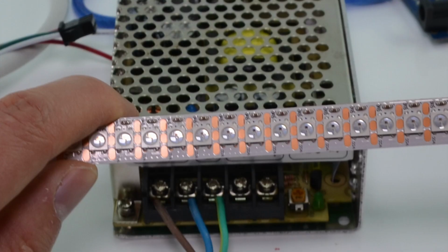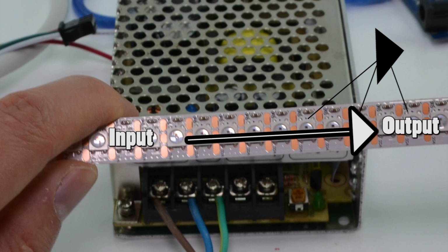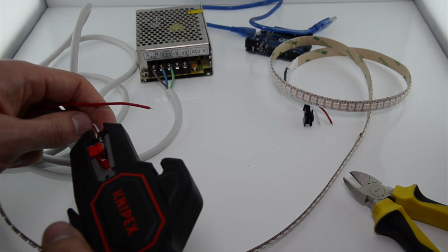On top of the LED strip there are little arrows, and these arrows will show you the direction of the LED strip. So there's one input side and one output side. On the input side of the LED strip you connect the Arduino, and on the output side you could connect more LED strips.